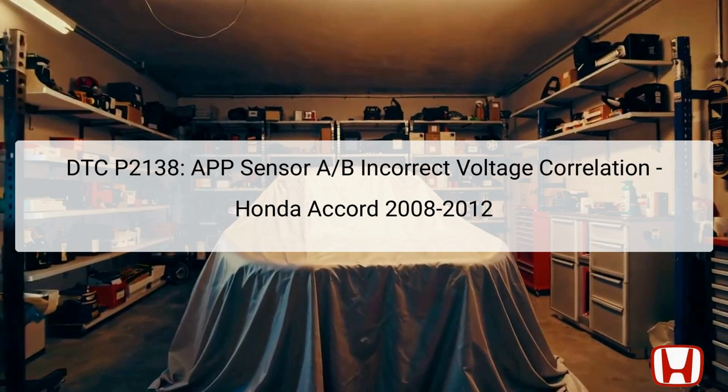These sensors are crucial for the vehicle's throttle control and overall engine performance, as they inform the ECU about the driver's acceleration intentions. Misalignment in their voltage correlation can result in reduced engine performance or abnormal driving behavior. The sensors are usually located on the throttle pedal assembly, which can be accessed by removing the driver's footwell cover.